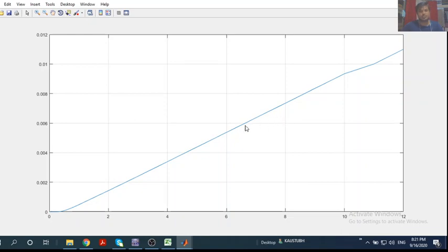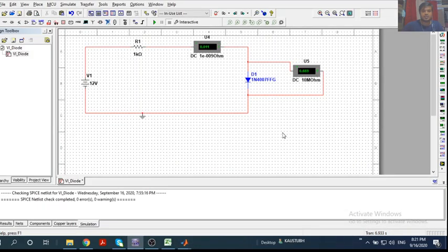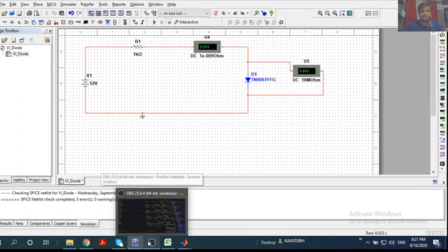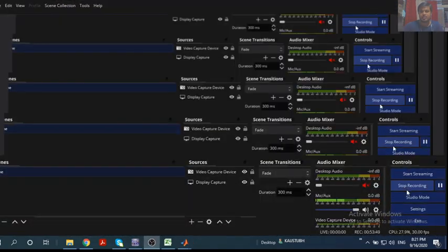So reciprocal of the gradient here will be the diode dynamic resistance. So what you need to do is take a tangent, like this. So vertically it will be del ID and this way it will be del VS. So del ID by del VS, reciprocal of that, del VS by del ID, will be your diode dynamic resistance. Okay, so that's all now. Thank you very much. If you find any difficulties, then let me know.